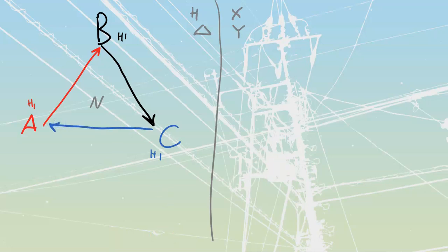Once I've got all of those in place, I can put my H2s off of everything. H2s and H2s over here. And now I'm going to draw in my low voltage side, and I'm going to have to look to make some parallels. Now, before we draw in the low voltage side, let's just set out where A, B, C, and neutral are going to be.